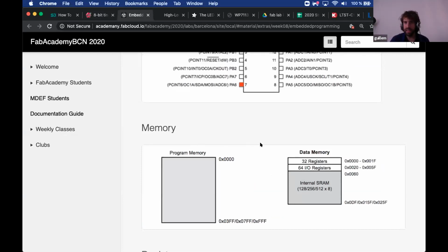And there's a specific part of it that is the most interesting to look at in such a datasheet. It's called the registers. The registers are quite a weird thing because we maybe talk a lot about many things, but we haven't yet introduced the registers. Registers are a specific kind of memory that, when we write things on it, actually does things. Let's think of the memory in our microcontroller as a bunch of cardboard boxes labeled with names, so we can identify them quickly. Some of these registers, usually these 32 registers at the beginning, when we put something into them, might actually do an operation with it.